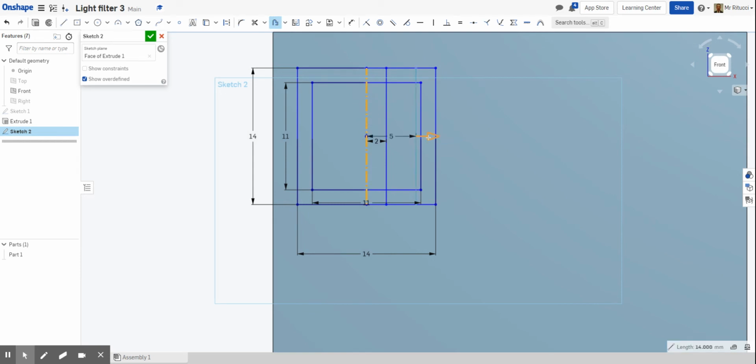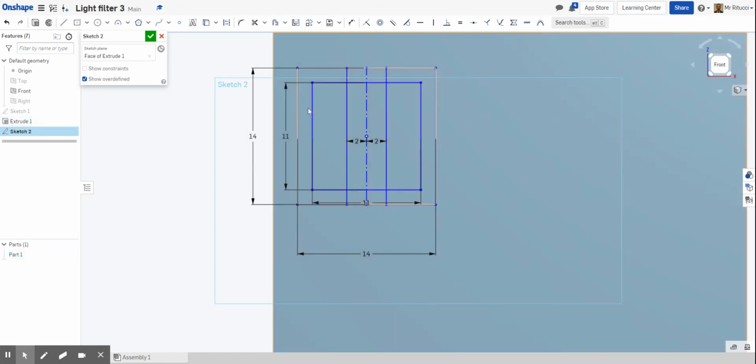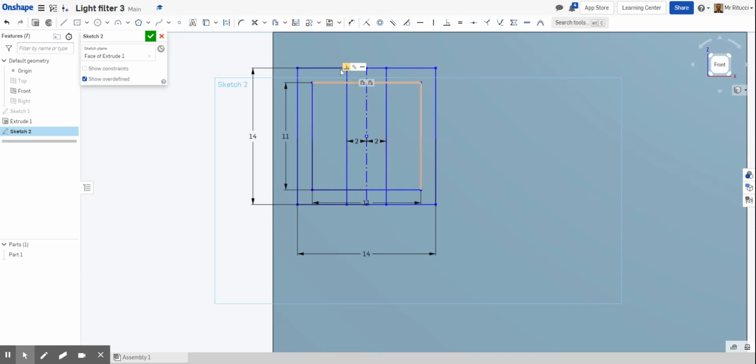The direction is wrong, so I'm going to click the arrow, and I'm going to click 2. If it turns all orange like that, just carry on, press enter, and then press escape, turn everything off, and click into a free space. Now I just need to do some snipping, because I want to keep these C shapes. So snipping tool, get rid of that, get rid of that, get rid of that, get rid of that.